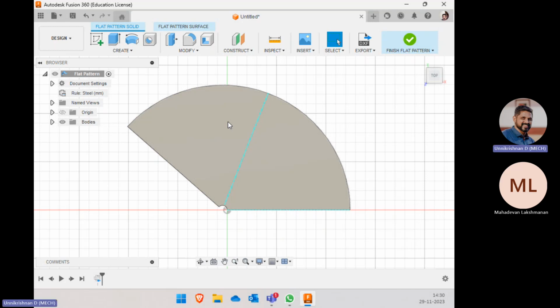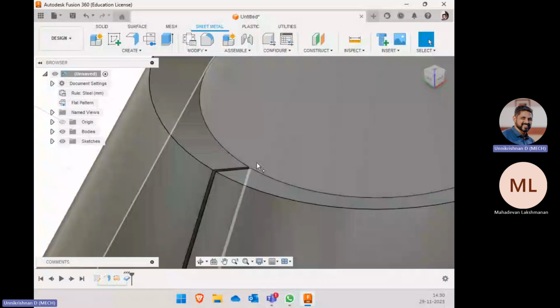And if you're going with 1 mm thickness of the sheet, then your thicken should also be done with 1 mm. But make sure that there is enough turning or bending radius available in your top portion when you section this. If I increase the thickness, it might intersect at some point here. If the intersection happens, then it will show an error. Earlier, the sheet metal rule was given as 1 mm; I changed it, therefore I could make the change.